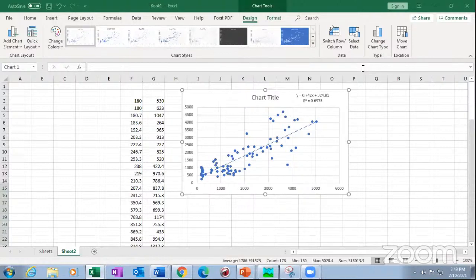The second thing is, you must have heard of the recession curve techniques for the estimation of groundwater volume. For that, you have to have hydrographs. If you don't have the hydrograph, there is a complete procedure, an eight-line procedure or algorithm. You apply that technique, then you will get the groundwater volume also. In that case also, HEC-HMS is useful.